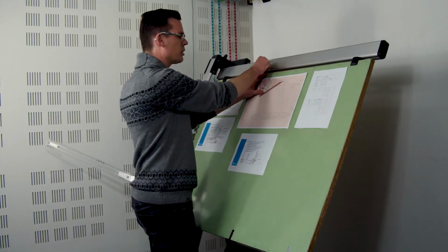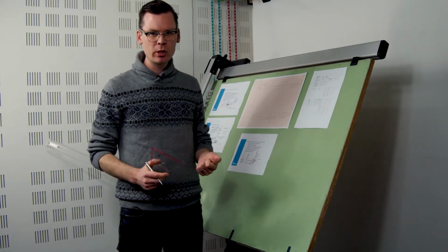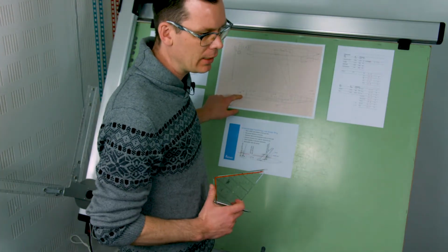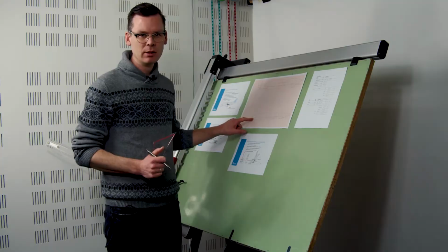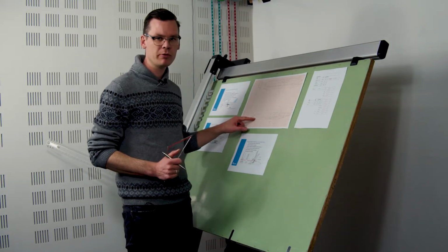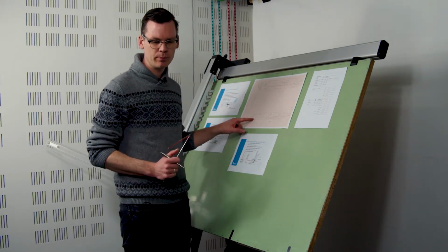Why am I doing this exercise? Because I already want to know, if I'm retracting this wheel, where it's going to end up. Why? Because I would like it to end up below my flight deck. Because below my flight deck I have some space that I'm not using for cargo.